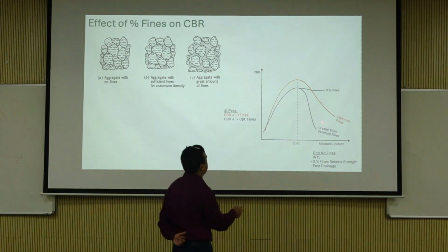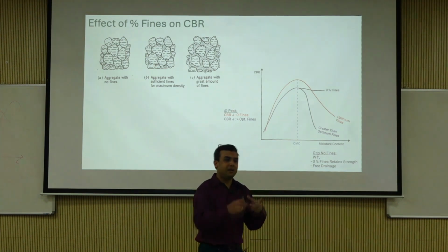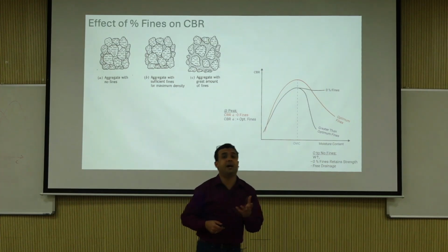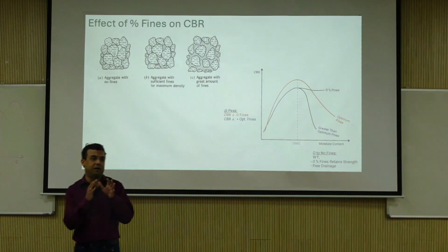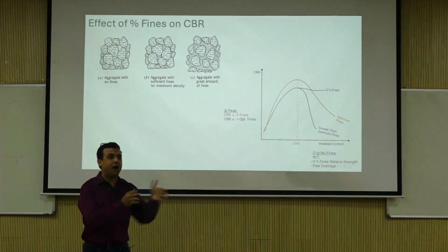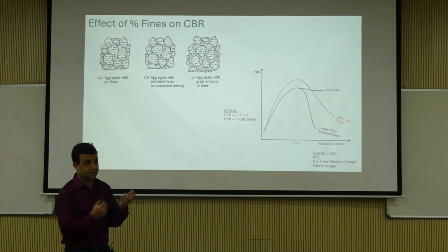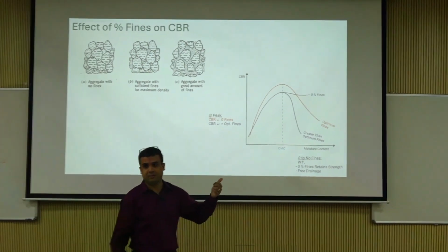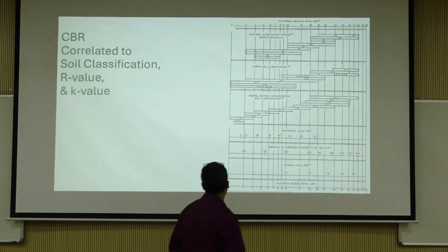Of course, with optimum fines, because the matrix is so stable, you have really good resistance. So that's the example, again, if you go back to the railroad ballast example, the fouled versus unfouled, that's what I was talking about, right? If it's fouled ballast, if it is dry, it can actually be really good sometimes. The problem is when it rains, it collapses, right?